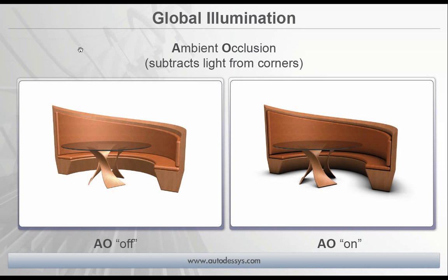We'll also take a brief look at global illumination. Now, the ambient occlusion option, that's not new in 7. We've had that for a long time. But to sort of finish the scene out here in part 2, we will have to render it for our final visualization rendering. And so I did have to turn the ambient occlusion on. I always use that because it just gives you more of a realistic render. It just subtracts light wherever two surfaces meet. I'll show you where that option is.